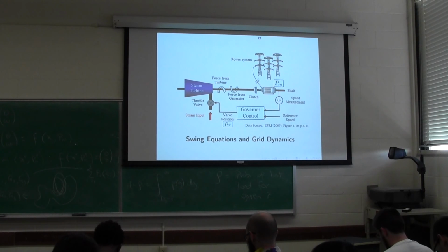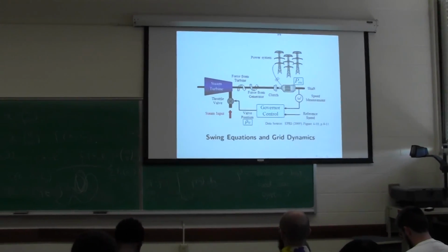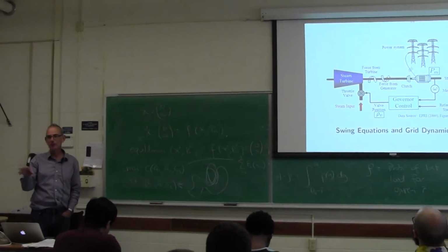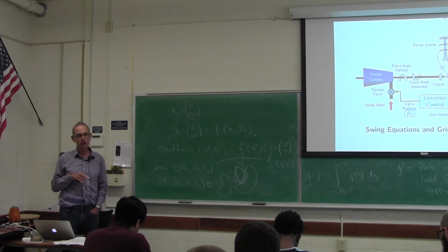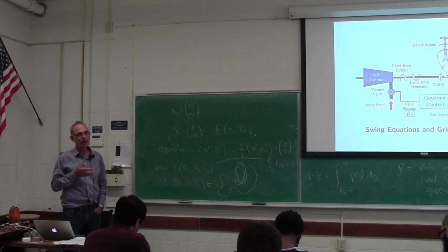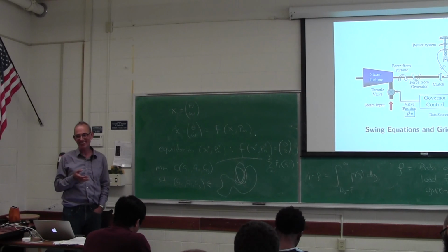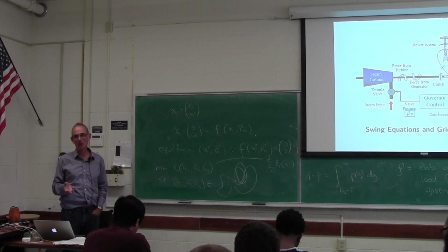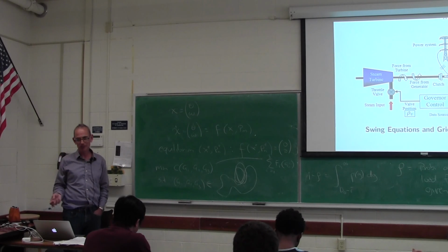Geothermal and all won't have power. What's that? Geothermal. Yeah, all these things. So that's the thing. Well, forget geothermal, it's such a small part, but wind and solar don't have any inertia. It's a curse. But it's a blessing that they have all these power electronics to do something. On the other hand, you can't make inertia from power electronics. Inertia is some sort of storage, and you can't do that through an algorithm, and you can't do it through power electronics alone. You're going to have something like storage, if you're going to have something mimicking governor response.